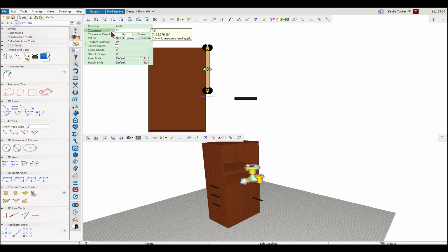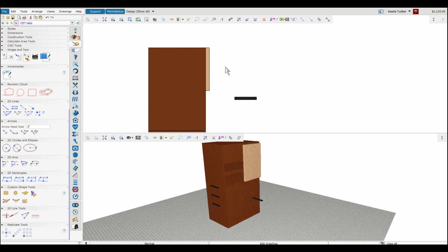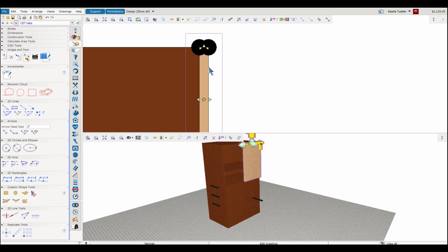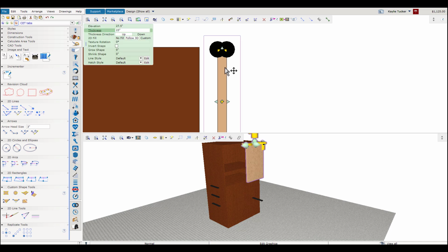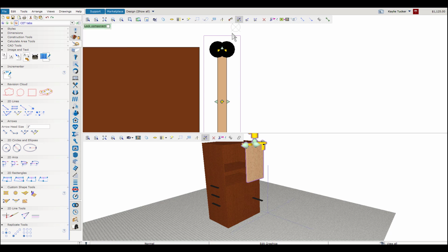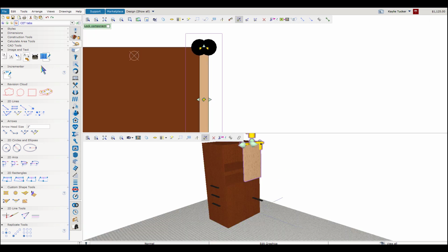All right, again, I knew this coming into it. I kind of did a little bit of cheating, but I'm just going to take that cabinet and make sure it's placed correctly using my positioning tool. And we're going to place that cabinet on there. And again, this is where I can adjust the width. Maybe it's 1/2 inch depth. So I can type that in my properties box.